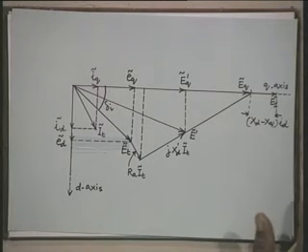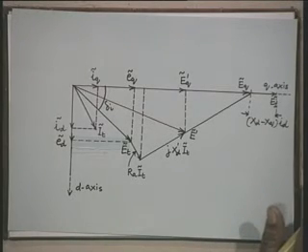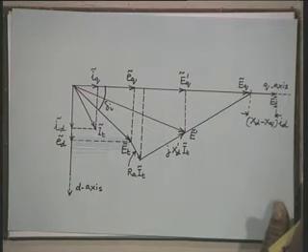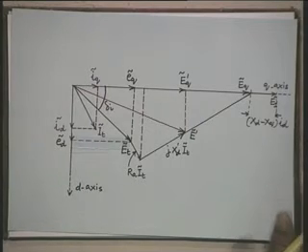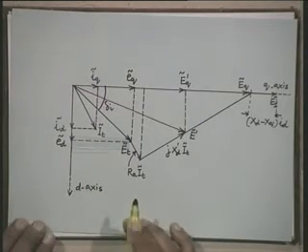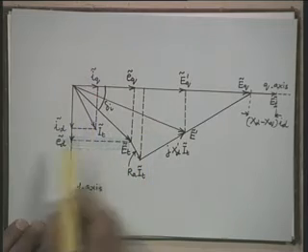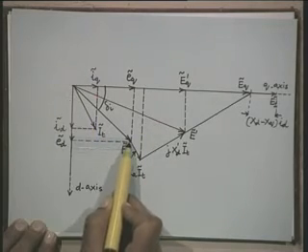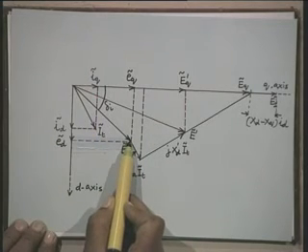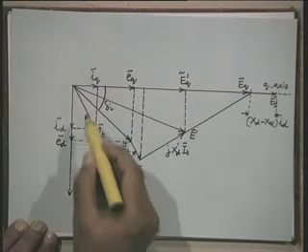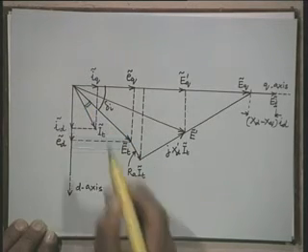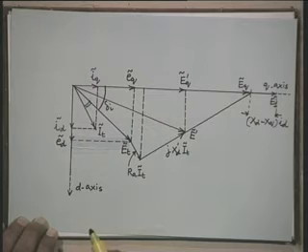This is not a very unknown phasor diagram to you, but to make these things complete, what we do is that you start with terminal voltage ET. Let us say this is the terminal current. The phase difference between terminal voltage and terminal current is always known to you.